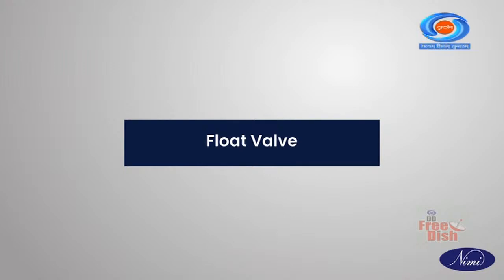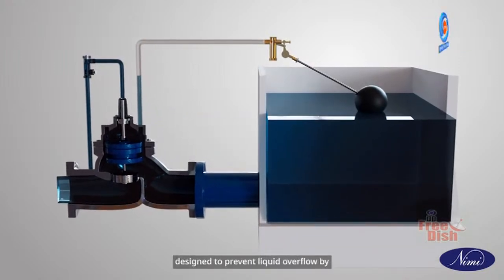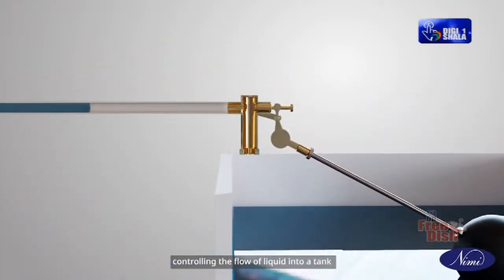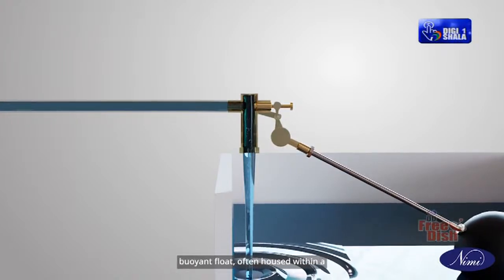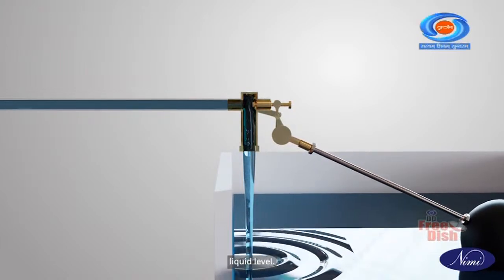Float valve. A float valve is a mechanical apparatus designed to prevent liquid overflow by controlling the flow of liquid into a tank or reservoir. Typically installed at the inlet of the container, the float valve utilizes a buoyant float often housed within a vacuum-sealed container to regulate the liquid level.